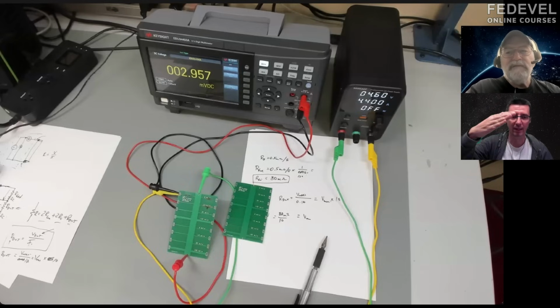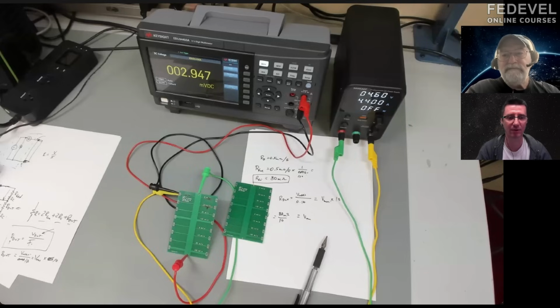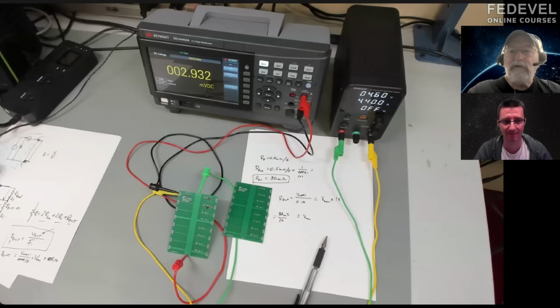So what do you think, if you double the layers, is it going to help, or is most of the current going to flow in the top layer anyway? Right. Well, we're talking about the DC current. The power distribution is DC. There are switching currents because of the IOs, which is a different issue to worry about. But for core logic, it's a DC current that's flowing.